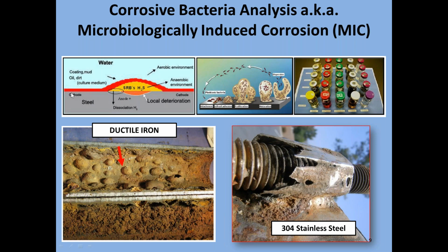See, this is a protective biofilm dome that they form, and the anaerobic bacteria will start to settle inside under the dome, and it's their byproducts that are very corrosive and lead to the rapid degradation and corrosion pitting, typically, of the metallic substrate down there. So these things are like bacteria. It's like when you don't take care of your swimming pool, it just starts to spread, algae everywhere. And here's an example of tubercles inside of ductile iron pipes. They cause some severe pitting of that pipe all the way through the pipe.